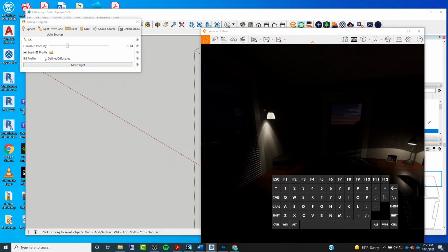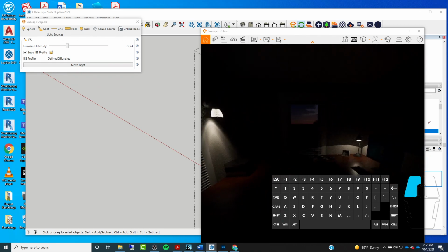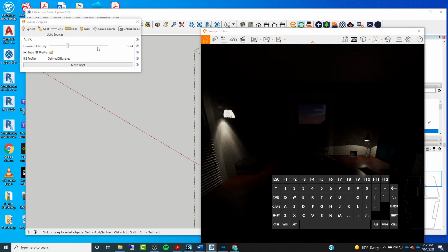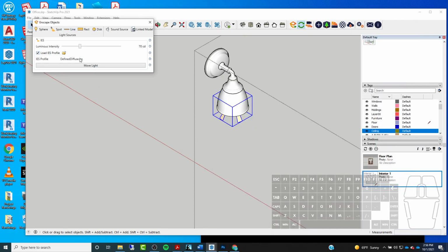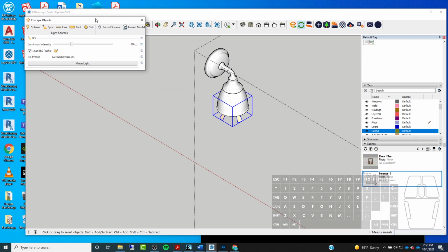And I'll go ahead and upload those to the Canvas page. So if you just want to download them from there and try them out, you can, but they're super easy to use. And then you can also use them within Revit. Whenever you're creating those light source distributions within Revit, like in the family editor, you can just click on those. And if you choose the parametric web option for the light source, you can specify one of these IES profiles. So it's really pretty much the same thing over there too, which is cool.